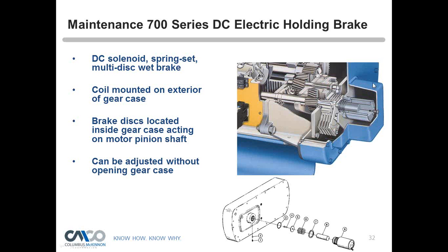On this 700, you see this kind of bucket, which I call a blue bucket, with a single screw in the center of it. If you take that bucket off, underneath it will be a blue cylinder, and that cylinder, which we see down here, is the brake coil. And there you can see the spring. There's the spring pressure, and that basically creates a plunger, right? You can see this rod here is a steel rod, and then a steel washer that gets connected to it.